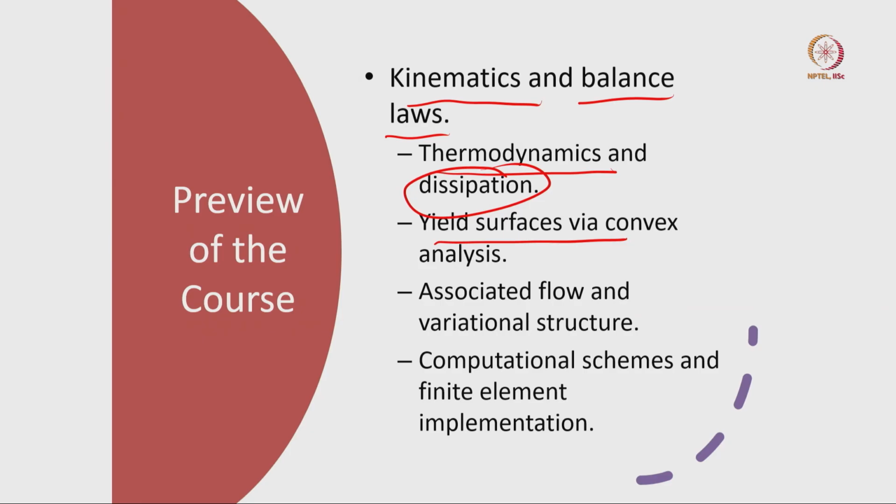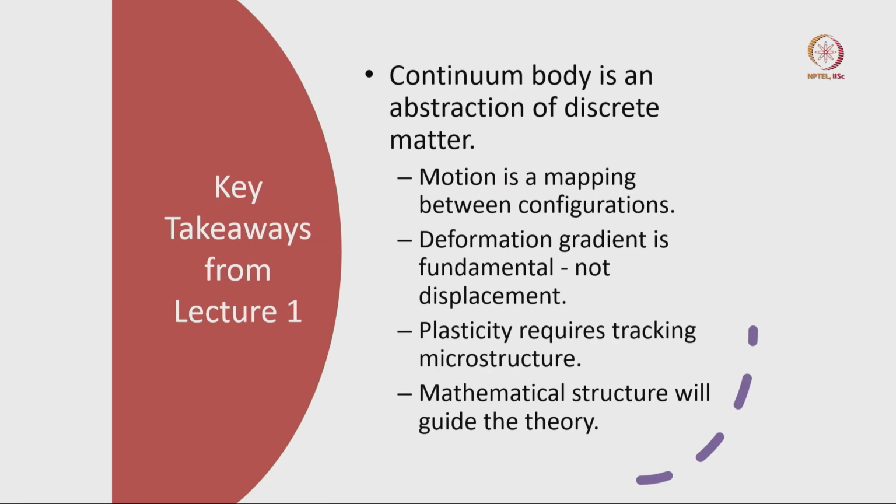We will define the yield surface using the language of convex analysis. We will talk about the associated flow rule and the variational structure associated with the evolution of the yield surface. The yield surface is a dynamic object, so we have a dynamic constraint in rate independent plasticity. We will talk of computational schemes and of course finite element implementation, so that you can simulate.